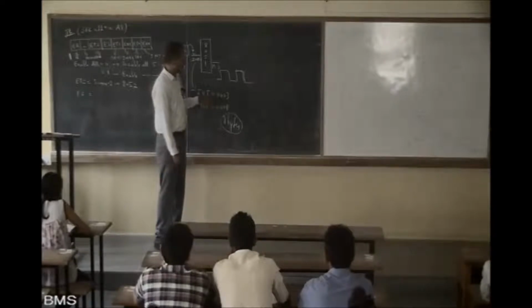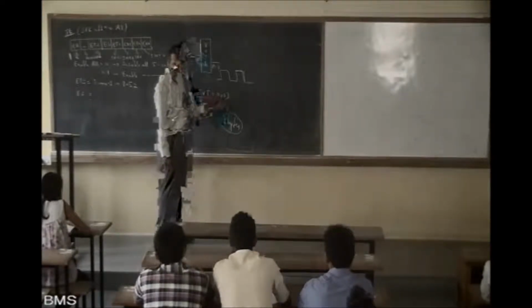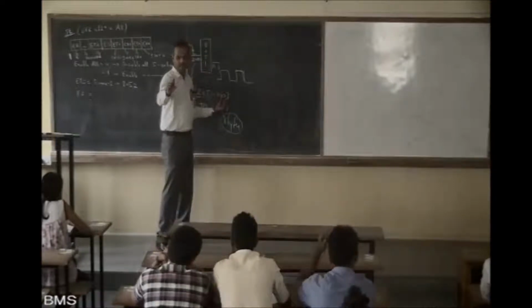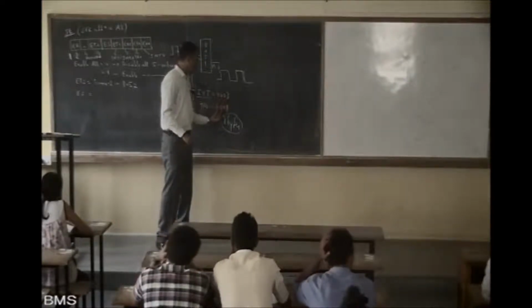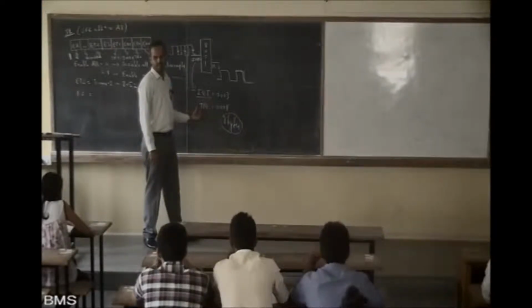Normally what people will do is they will just write LJMP here, which will go and sit in here. It has to be only 8 bytes. If it is more than 8 bytes, you are interfering in some other interrupt area. Are you understanding this?